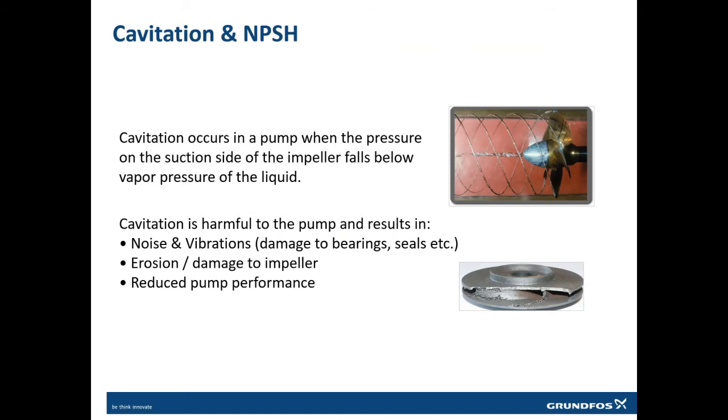Now coming to the last point of today's pump basic course. This topic is about cavitation and NPSH. This is usually known as the pump killer, because if cavitation is happening in your pump, you will hear a very loud cracking noise. It is like you might not be pumping water, you are pumping stones. So you will hear very loud sounds of cracking inside your pump. You will feel a lot of vibration inside your pump.